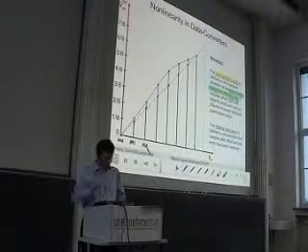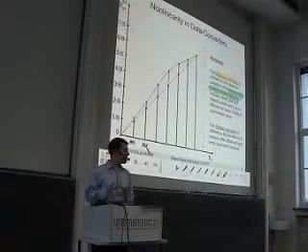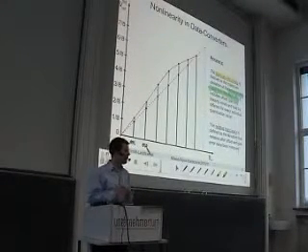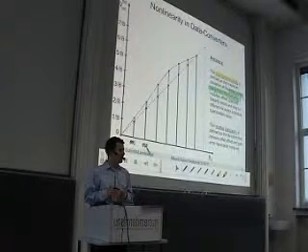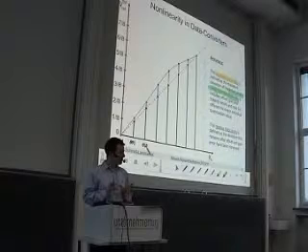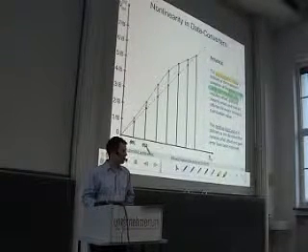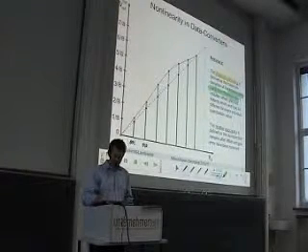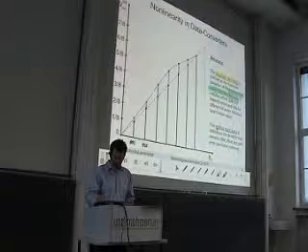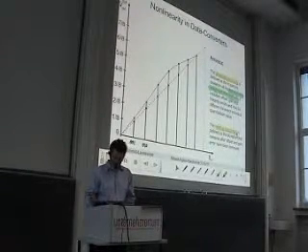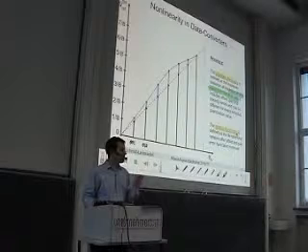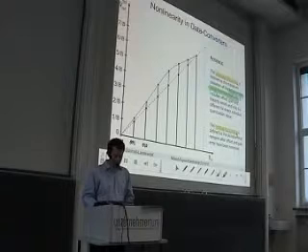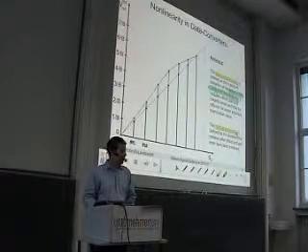Well, now you might say, interesting, but what we want to do here is to measure the non-linearity. We have seen that there is also offset and a gain error, and these errors are not non-linear. These are errors, yes, but they are linear errors. So if we want to focus on the non-linearity, we can go for the relative inaccuracy, and the relative inaccuracy is defined in the same way. However, first the offset and the gain error are removed, and then we measure the non-linearity in the same way.